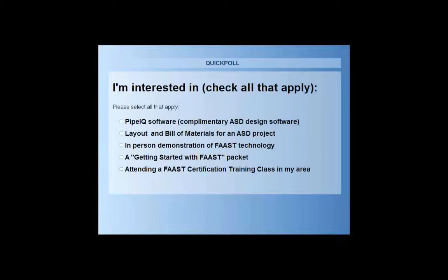All right, very good. Next question relates to covering an area that's also protected with fire-rated walls, and they're wondering how they would run a piping network over, around, or through fire-rated walls, so that you could use the 8,000 square feet to the max. Okay. Yep, sure. Obviously, when you're penetrating a fire-rated wall, you have to take all precautions as far as the sealing of the holes and the penetrations.